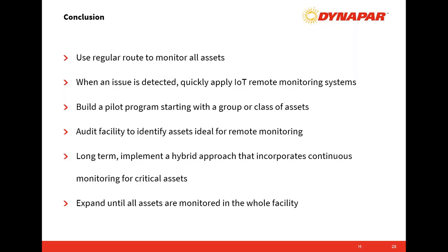Another thing to jump into there is our triaxial sensors, so we're looking in all 3 directions at the same time. But importantly, we're getting temperature data. Several customers have seen sudden spikes in temperature, which is an indicator that there's an issue. A lot of times you start having problems with windings, and they get real hot. With bearings, maybe at slower speed, we don't see as much impacting in the time waveform or in the frequency analysis, but the temperature is going up, which tells us there's a bearing problem. So there are a lot of things that remote monitoring can catch that would simply be overlooked.